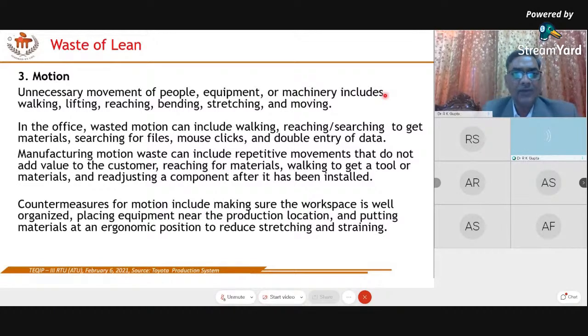And then the most important part in cellular manufacturing is the movement of the part. The machines are arranged in an inline layout or any other way of layout, so that whatever kind of operations can be performed, we have to arrange like that. One is a repetitive operation. Like machine number one is supposed to be a lathe machine. Initially, we are doing the facing operation. Then the second operation is the turning operation. Then there are some other operations to be performed, like drilling or chamfering operations on the lathe machine. So this is the repeat operation.